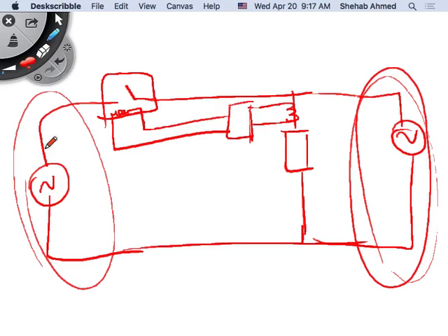How do you protect your system this way? So maybe you need another CT here, right? If you put a CT here, okay, that's a good point. Actually, if I put the CT here originally, forget about this one. If I put this CT originally here, and as soon as I see an increase in current, I disconnect, okay?